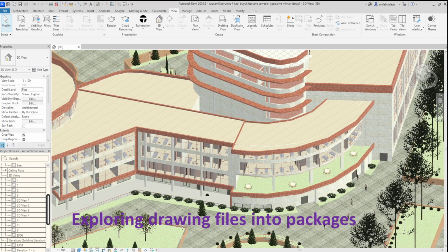The drawing files package consists of civil, coordination, landscape, map, structural, and architectural models. This process is repeated at established intervals in the design process. See the change and refresh the link in Revit to understand the latest change.